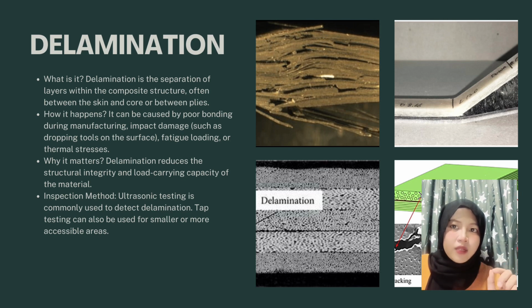The cause of the fiber delamination is impact. As an example, we drop a part of the composite material itself, or our laminate part, or our tool on the laminate surface. The second cause is manufacturing defects such as air bubbles, poor resin bonding and contamination. The third factor is moisture or thermal cycling, for example repeated heating and cooling, or the humidity when we are doing the laminate.